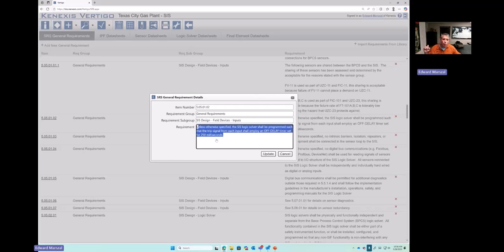The absolute worst way that you can generate safety requirement specifications is to take clause 10.3.2 of IEC 61511 and try to turn it into a fill in the blank form. Please do not do that. You're going to do all kinds of error-prone, repetitive work.